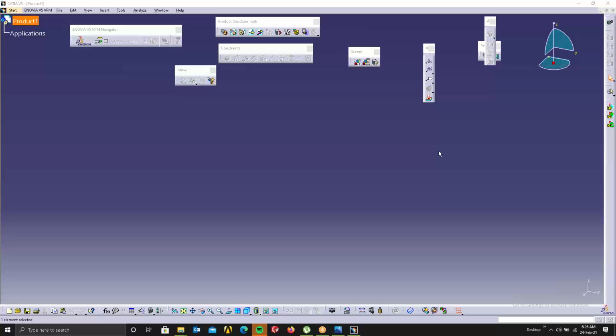Just for not mentioning a flatness of 0.1 at this location and 0.1 at this location, you lose some 30,000 rupees, more than that. For a brazing cycle it's 60,000, so more than 1 lakh, 1.5 lakhs you will waste just for not mentioning this.